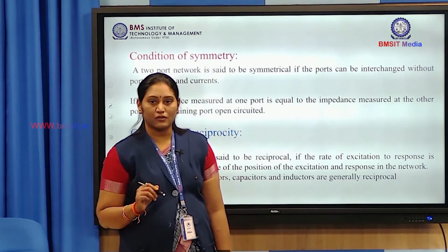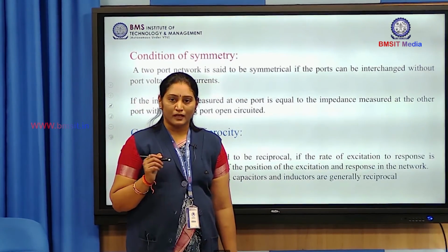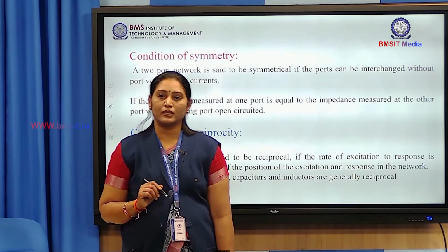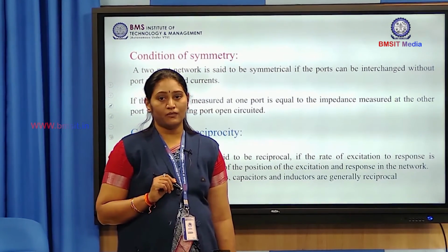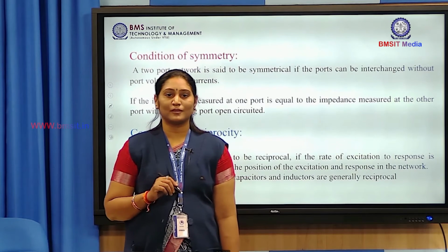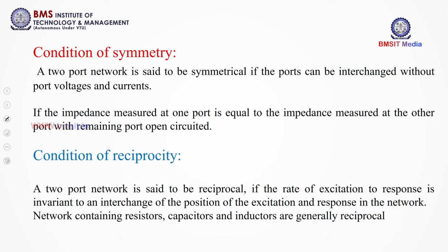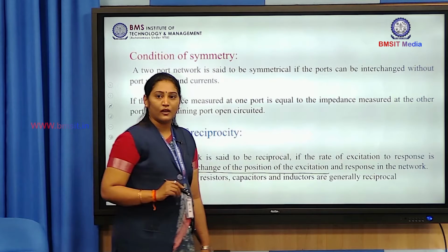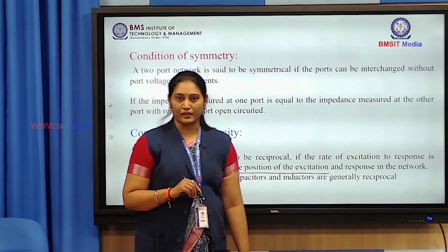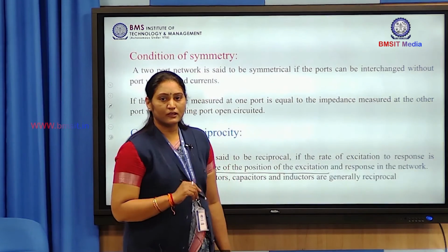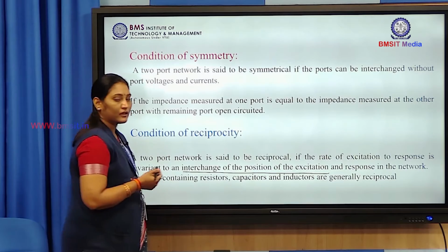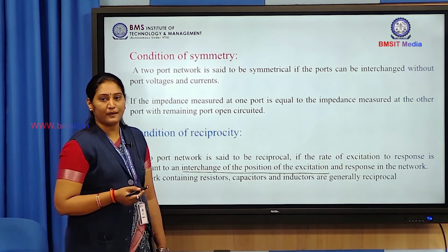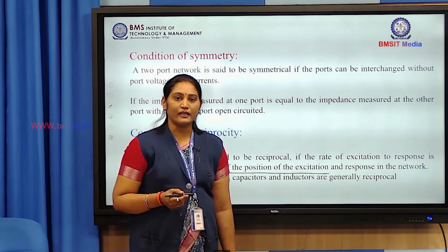The two port network is said to be reciprocal if the ratio of excitation to response is invariant to the interchange of position. You have to see the interchange of the position of the excitation and response in the network. This type of network we call a reciprocal network. Networks consisting of resistors, capacitors and inductors are generally reciprocal.